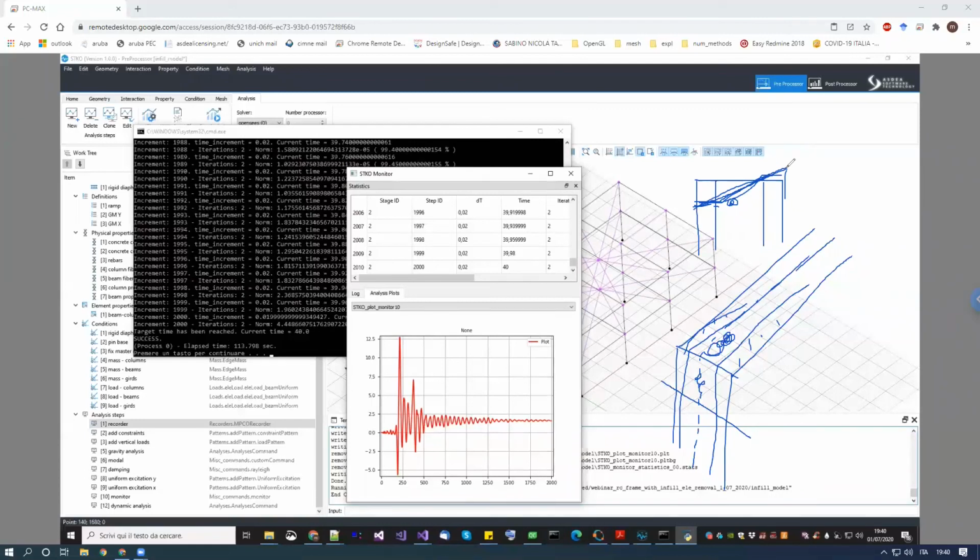For example, if I have plastic joints instead of ordinary mortar. No, I mean, you can model mortar with shell if you do something like this, for example. If you have bricks and mortars here, of course you can model the mortar because you're modeling the mortar in the plane of the shell. I'm talking about modeling some sort of mortar or soft material along the thickness of the shell. Those are two different things. You can do this as I did in many other examples, but you cannot do this one.